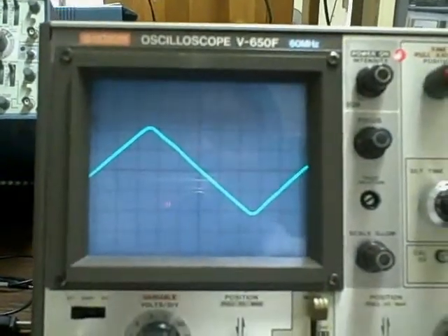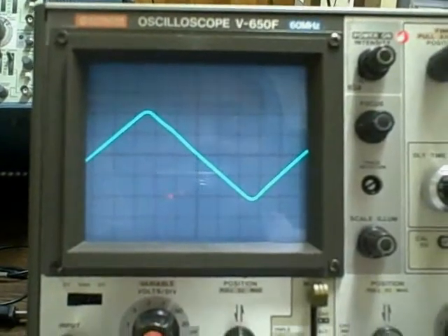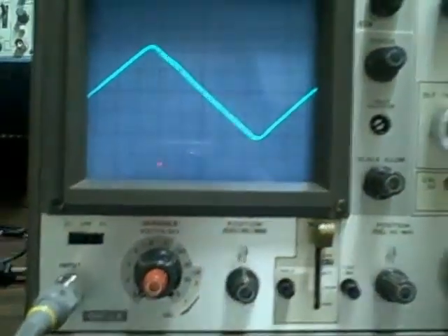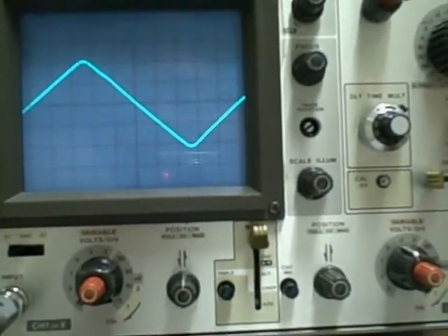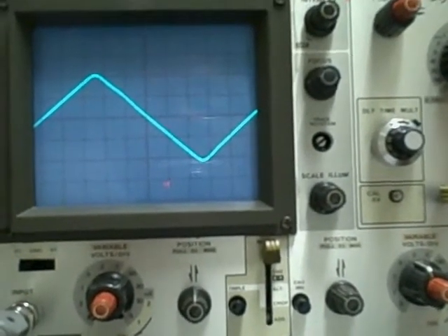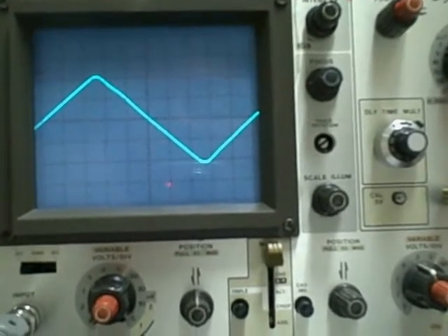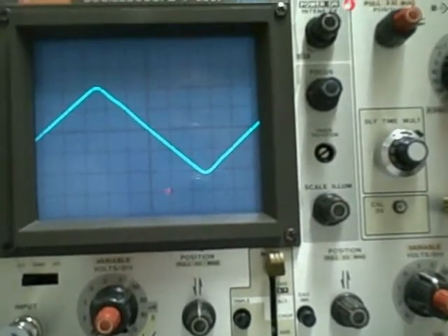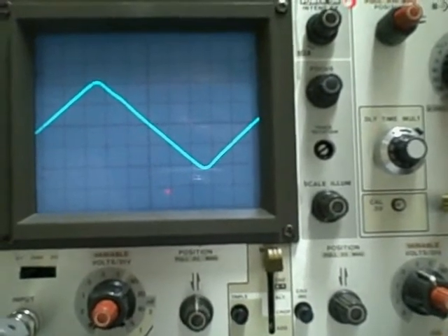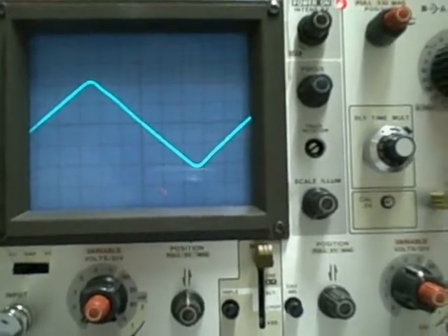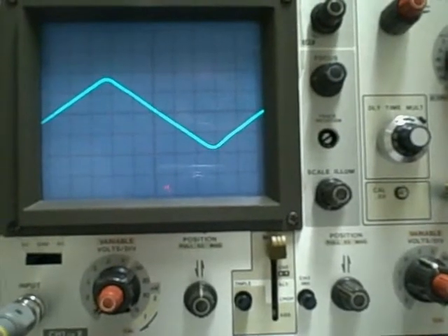and we're running 20 volts peak to peak. We're in the 5 volt per division range. Now I'm going to change my range to 2 volts per division. We can go up 4 and down 4, so that's 8 volts. Right now I'm going up 10. I can't handle that, so I'm going to drop my voltage down to 5.